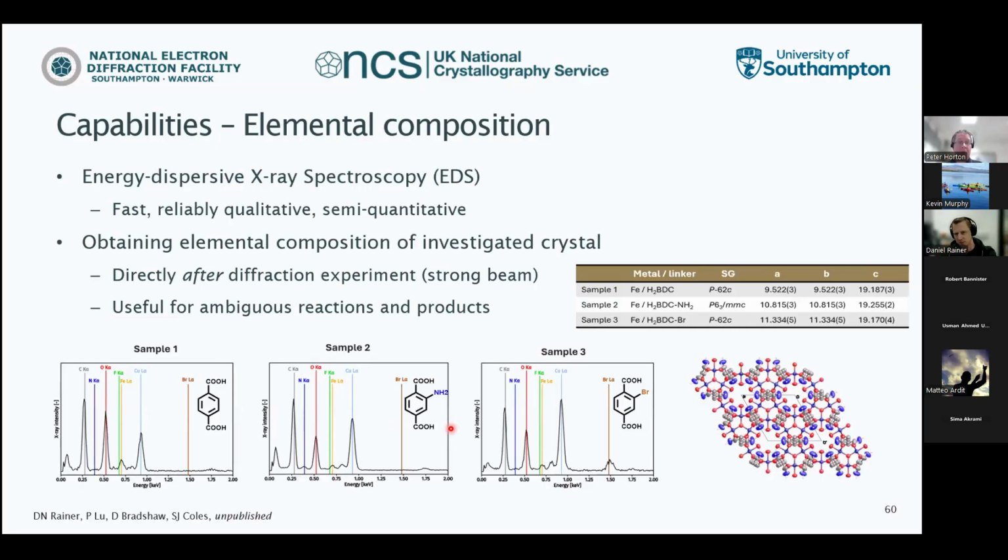Lastly, I think this came up for those of you who are aware of SEM and TEM or have seen the recent talk in the seminar series as well. There's EDS. So EDS is energy dispersive X-ray spectroscopy, and this uses X-rays that are produced due to interaction of an electron beam with the sample. So these are produced all the time when a strong electron beam